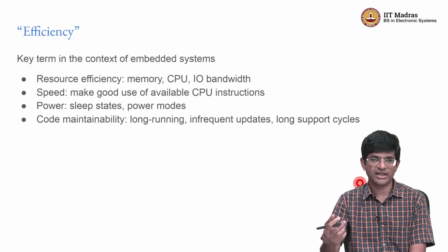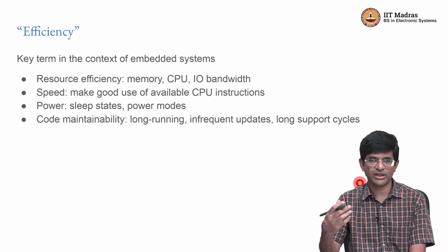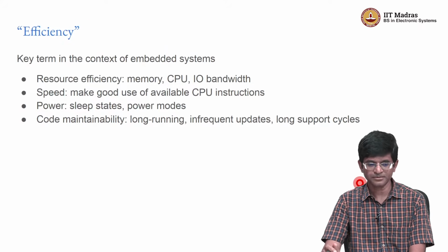Whereas there are other protocols like Bluetooth which have better low power modes. In other words, it can actually go into kind of a sleep mode and wake up at a much lower frequency than what Wi-Fi would, and therefore has a better profile in terms of the power that gets consumed over a period of time, which finally translates into the total energy that the system is burning up.